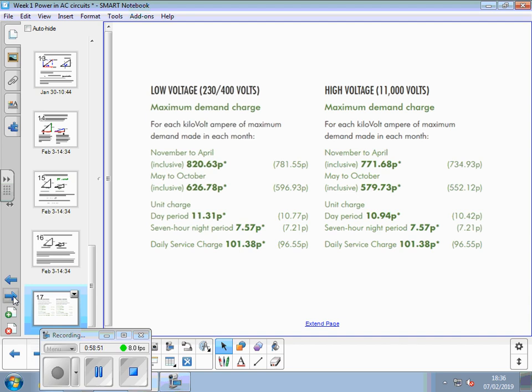Now the issue comes when you've got plant that's switching off and on load all the time, big motors starting up and stopping, your power factor is constantly moving. So that means you have to have automated power factor correction. It's measuring the power factor and switching PFC capacitors in and out accordingly to try and maintain a good power factor. So it's not a topic I certainly don't understand automatic PFC. I've never had anything to do with it. But I do understand the principles of putting capacitance in the circuit to counteract the inductive load.